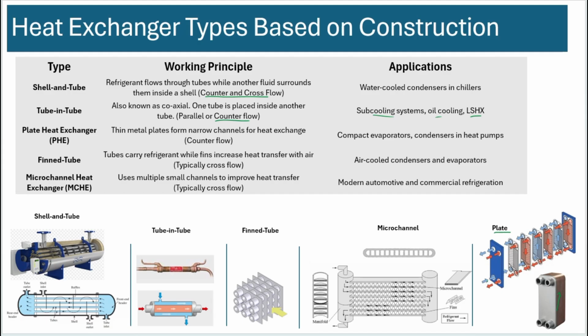In this case, the orange or red represents one fluid and the blue represents another. You can assume the orange is the hot and the blue is the cold one. They alternate between each gap. If the hot fluid is going through the gap between these two plates, the cold fluid will flow in the next one, and then the hot fluid in the next one, etc.